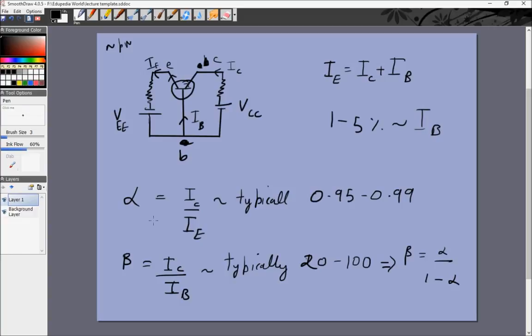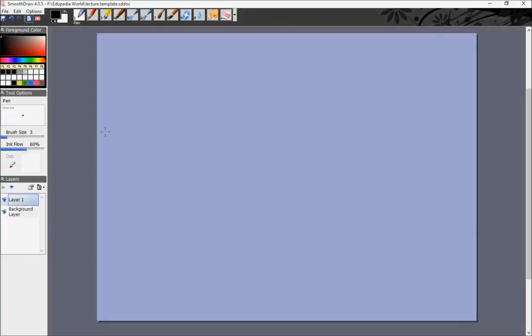of a transistor. Now, a very important use of a transistor is in amplification. When you have a small signal and you need to convert it to a larger signal. A small input voltage signal has to be converted to a larger input voltage signal of obviously the same structure. So we'll see the working of a transistor as an amplifier now. And for an amplifier, a transistor is used as the NPN transistor in common emitter mode.